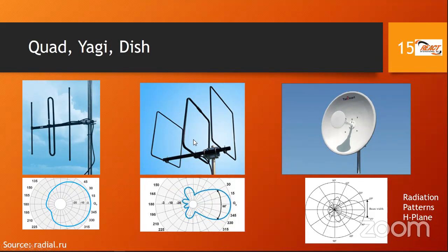This next antenna on screen is called a quad antenna. So notice the configuration of the elements. You have the same center or driven element that you feed, and then you have a reflector element and a director element. And that means that the signal travels in this direction strongest. It's a very directional antenna. And if we were to look at the radiation pattern for this antenna, notice that it's very strong in the forward direction and relatively weak, even weaker than the previous diagram. Notice it's very weak to the back here and very strong to the front.